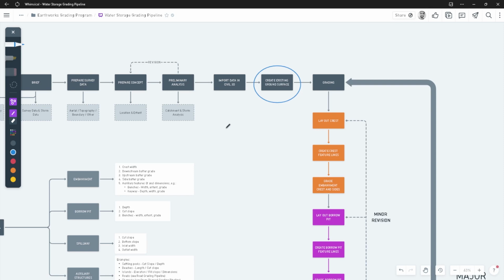It is what will allow us to determine those volumes and to measure how much these elements are going to cost, and to get an idea of, do they need to be balanced out? So for instance, does the dam need to be balanced out against the borrow pit? Because it is from the borrow pit that we get the material to build the dam.